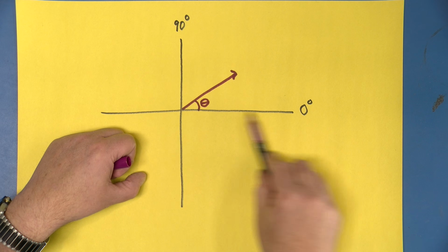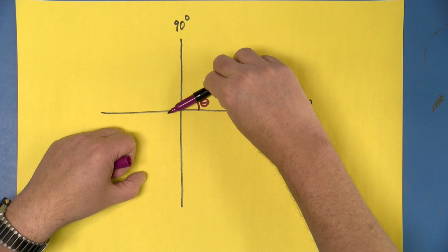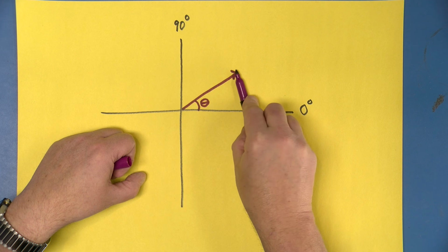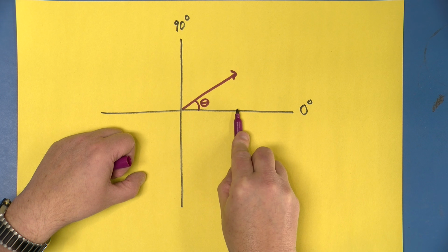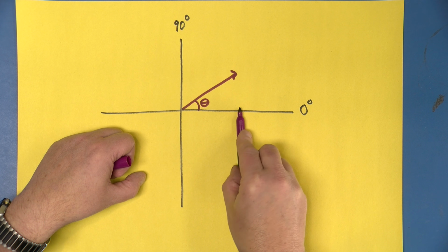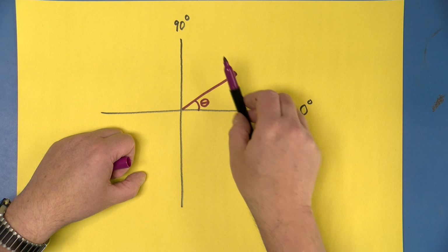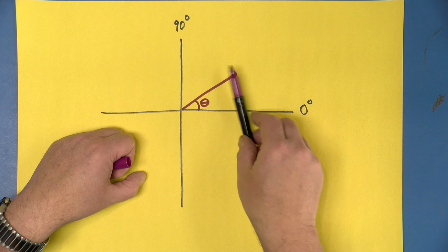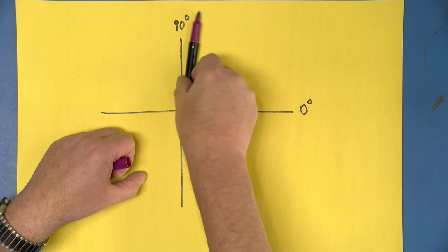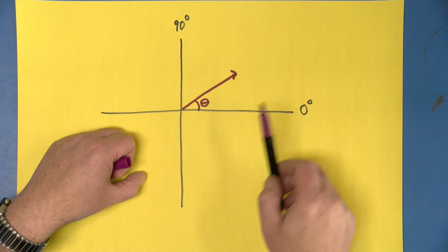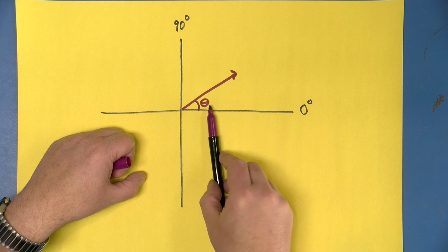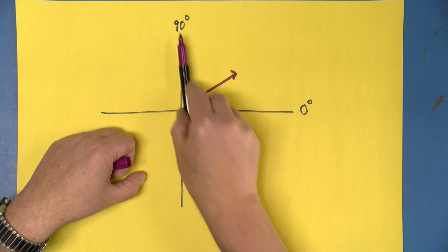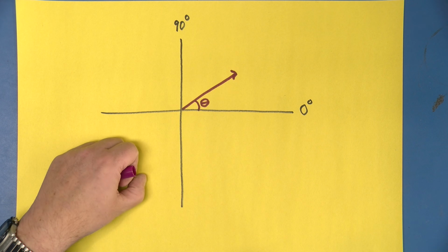So if we had a resistive load, this arrow would be down here, the phase angle would be 0, all the current would be a real current or in phase current. If we had a reactive load like a perfect inductor, maybe a superconductor inductor, this arrow would be all the way up here, and the angle would be 90 degrees. We'd have no in-phase current. We'd only have reactive current.